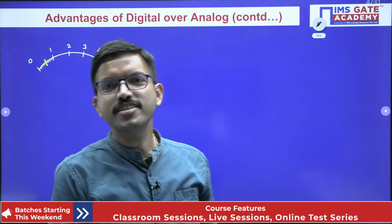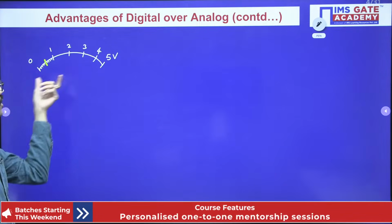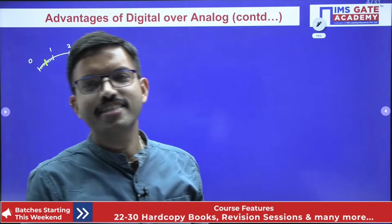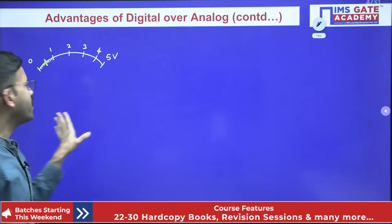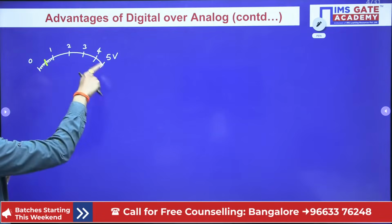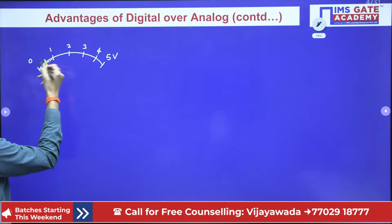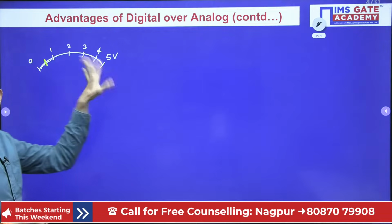Hi Nikhil, good evening. I hope you can guess. When you are doing the experiment, if you want to find the voltage, you will use a voltmeter, right? Yeah, thank you Nikhil. You will use a voltmeter. You might have the meter reading like this, right? You will be having 0 to 5 volts, and here the scaling will be like this: 0, 1, 2, 3, 4, 5, and between 0 to 1, 10 small divisions. Similarly, 1 to 2, 10 divisions, 2 to 3, 3 to 4, 4 to 5 like this, right?